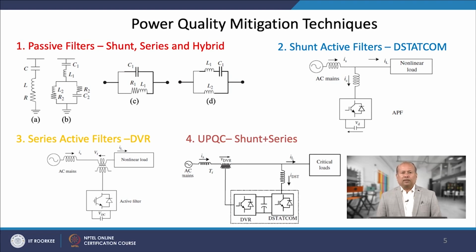As a result, a large filter size is required, which causes overcompensation of the reactive power. In consideration of the above-mentioned limitations, active power filters are an important and flexible alternative to compensate voltage and current related power quality problems in distribution systems. The concept of the active filter is relatively old, but it has recently become popular due to advancements in power electronics and their control strategies.